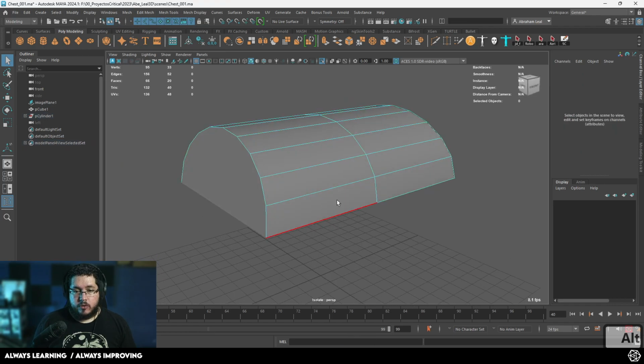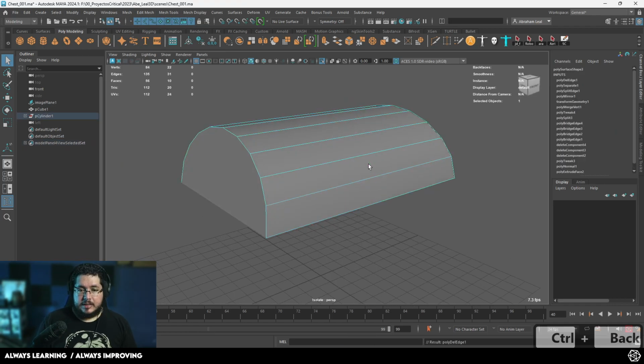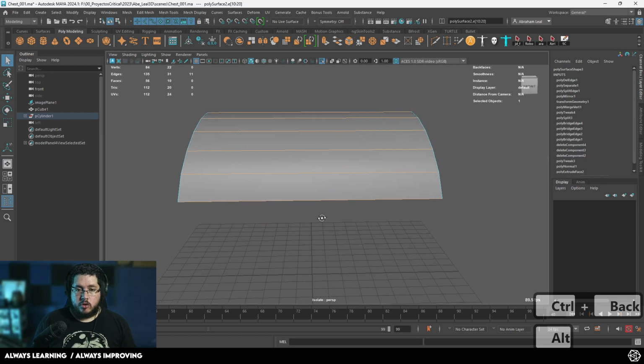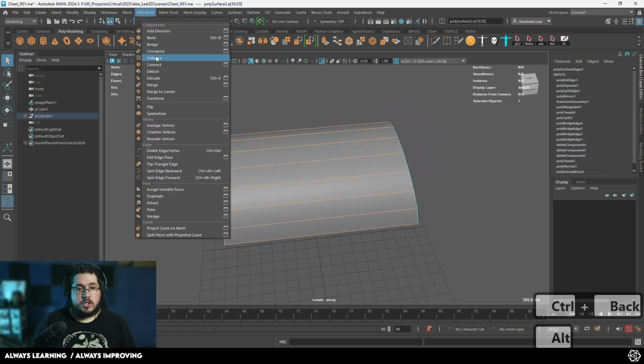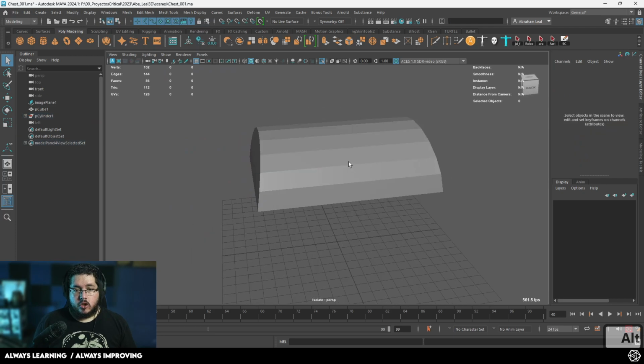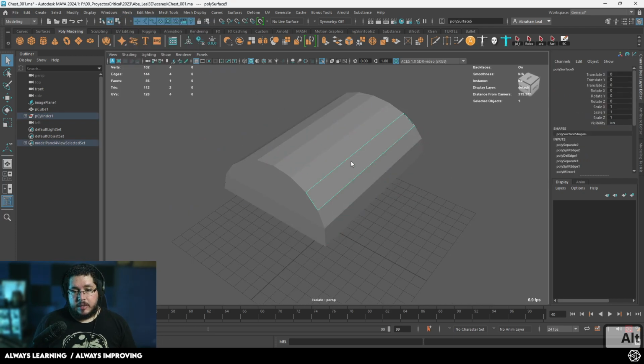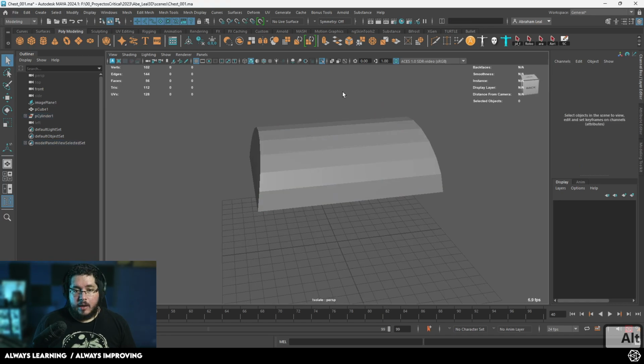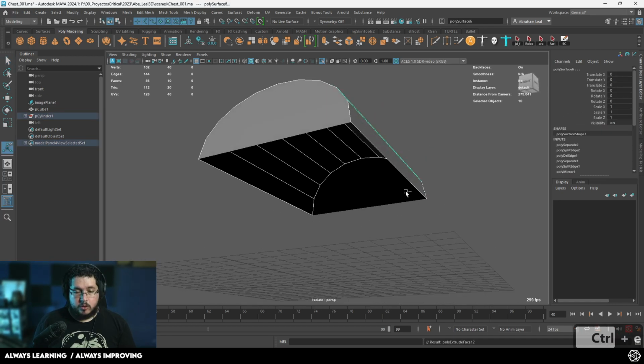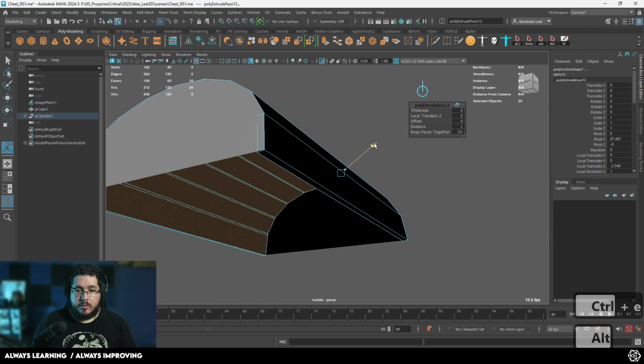So now if we go, for instance, to this guy right here, I'm going to delete this center line, and I'm going to grab pretty much all of the edges again. I'm going to say edit mesh and detach again. So now each individual face, as you can see right here, is a separate element, it's a separate plank. And we can grab all of the planks, do another Control E, and extrude them in.